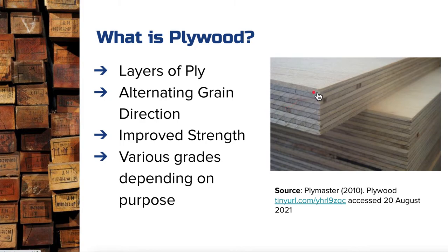And that's because whenever you see end grain here, the layer above it, the end grain is actually on the other edge. Now I know you can probably see these little rings there, and they probably look like growth rings. I'm really sorry that that's in the image, but that's actually marks coming from the circular saw blade that's cut these. So don't be deceived there. Light color is the side and end grain. So what they do is actually lay effectively sheets of veneer over top of each other, but they swap them around.